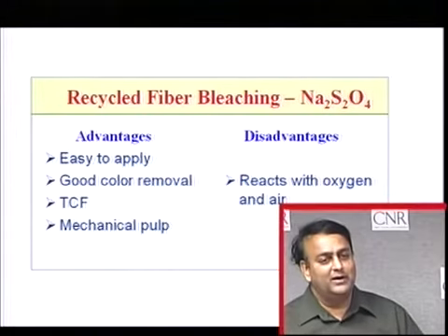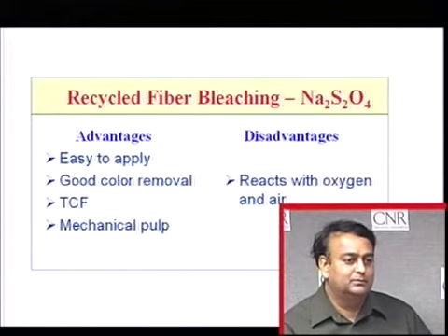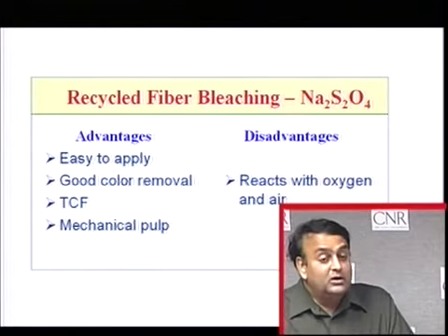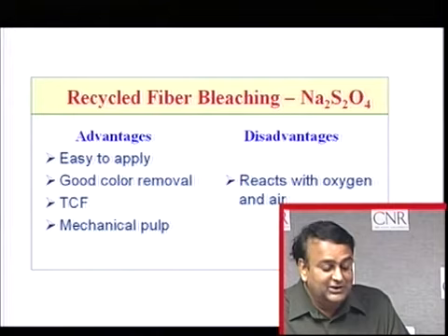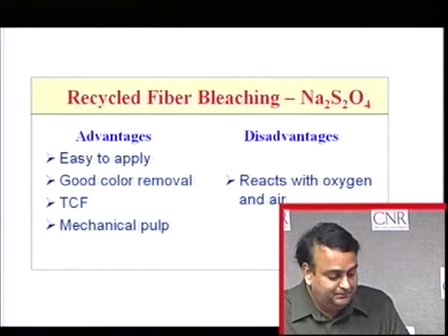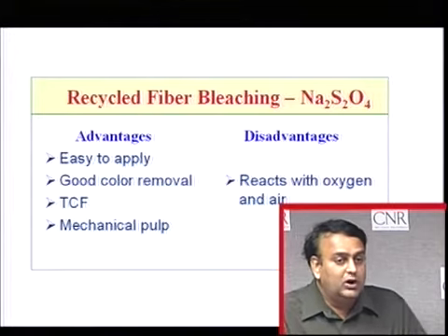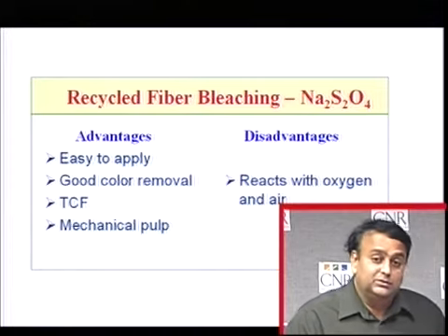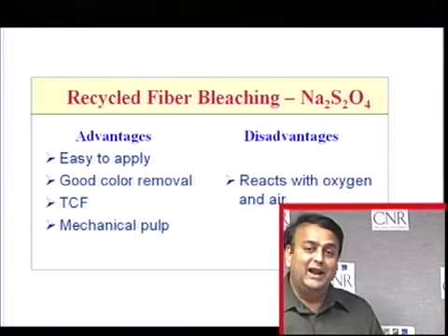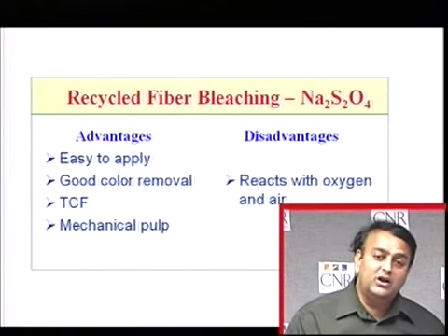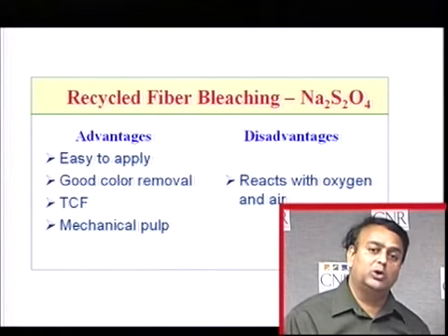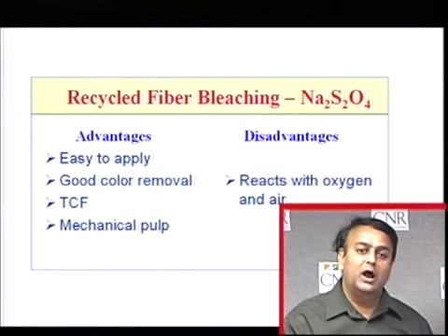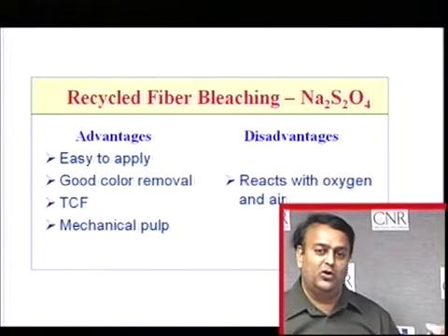What are the advantages of hydrosulfide? Very easy to apply. It's in liquid form, you just pump it, it goes into your system. Very good color removal. Some of the dyes were completely removed to make it white. And it has a total chlorine free label. And it works on mechanical pulp. So if you recycle fiber, office waste contains, let's say, some amount of newsprint, hydrosulfide can attack lignin and also attack dyes. So it works on both. Decolorization takes place and brightening, the modification of chromophores on the lignin, takes place.